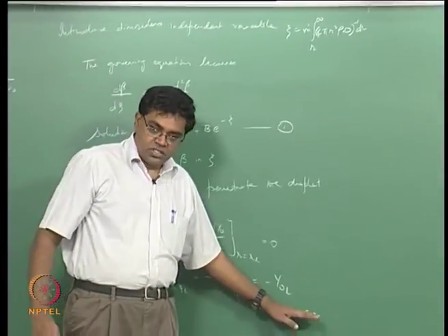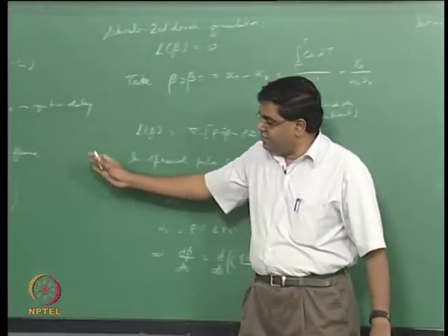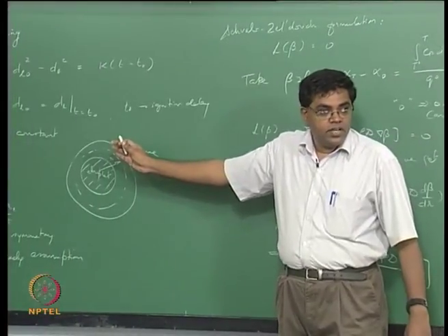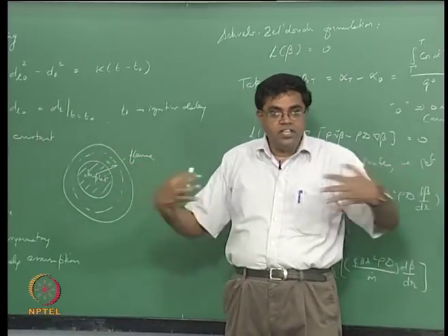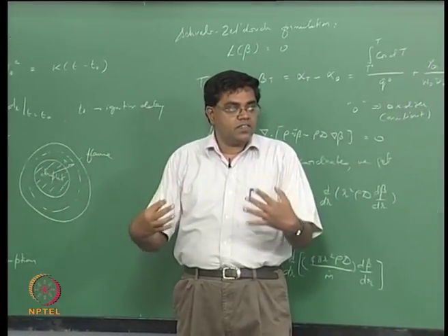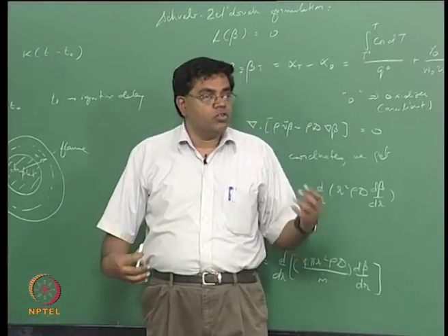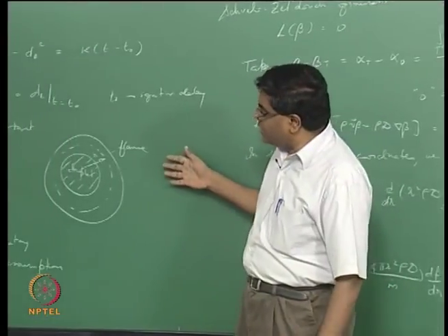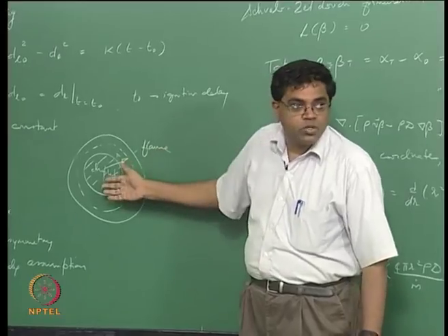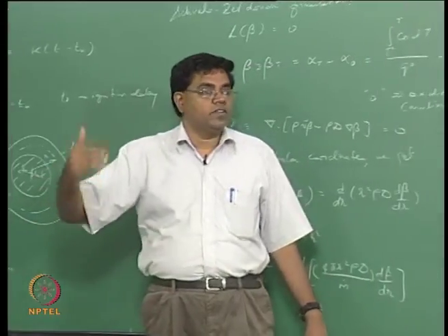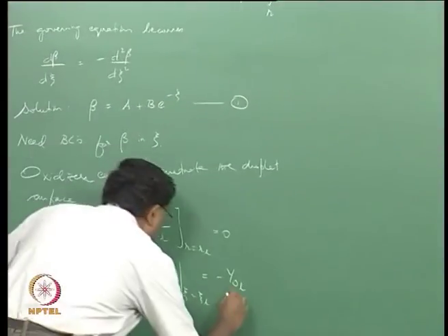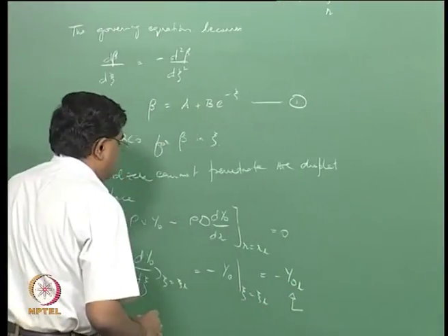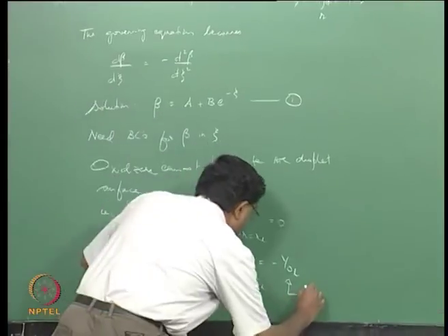In combustion you will have the situation where the oxidizer is getting consumed in the flame. In evaporation you don't worry about a flame, it is just the heating from the outside that is causing the evaporation, and you will still have ambient gas trying to diffuse up to the droplet surface and hold a certain concentration there. So this essentially is the oxidizer concentration at the liquid droplet surface.